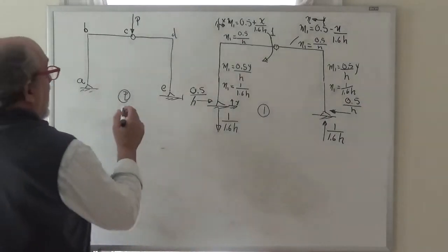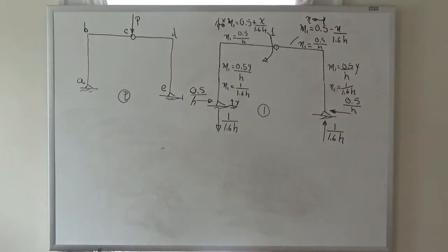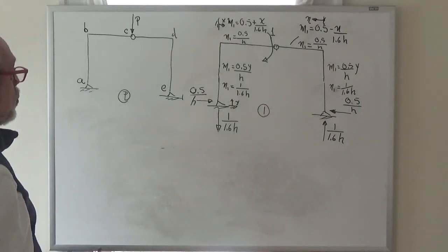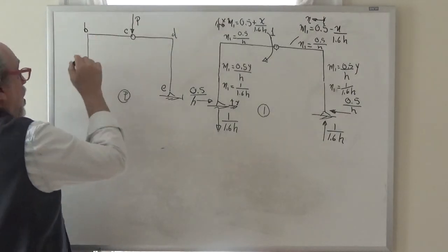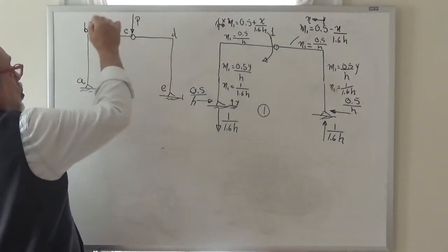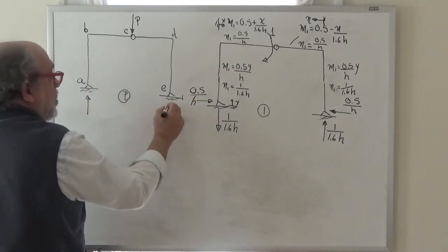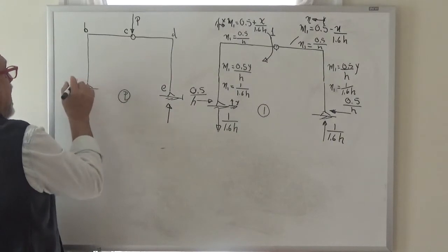So first I take a look, well actually let's see, maybe I don't need to complicate the situation so much. It's clear, I'm going to assume that this is obvious. It's clear that if I take a free body diagram of the complete structure, I'm going to have a reaction here, and two horizontal reactions also, right?